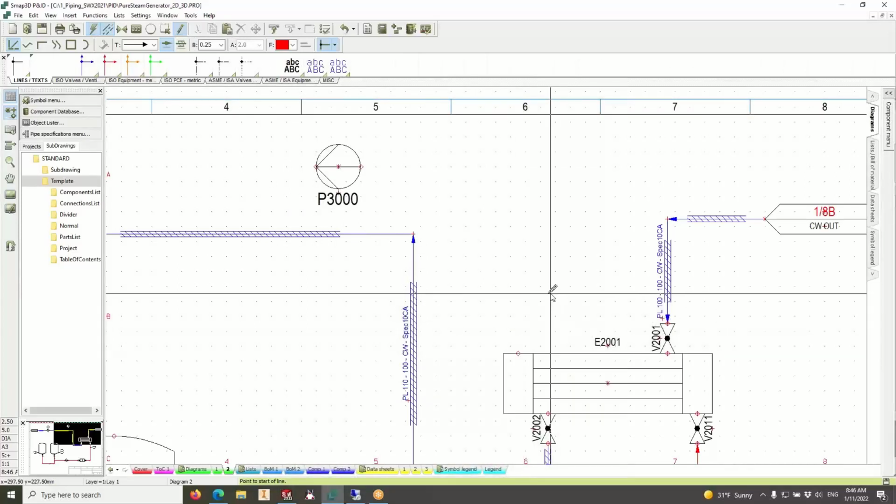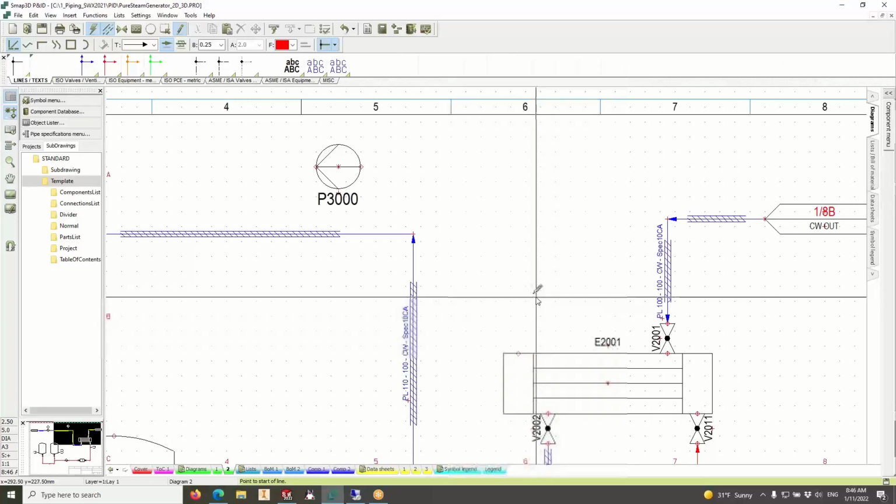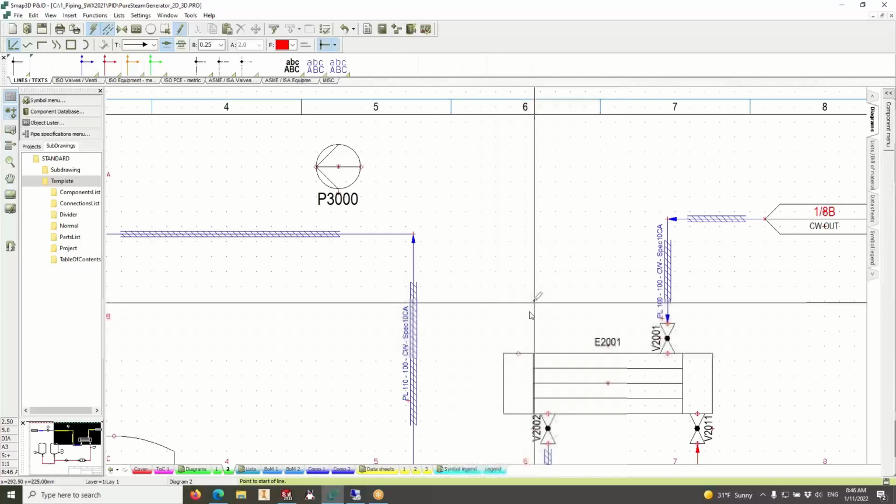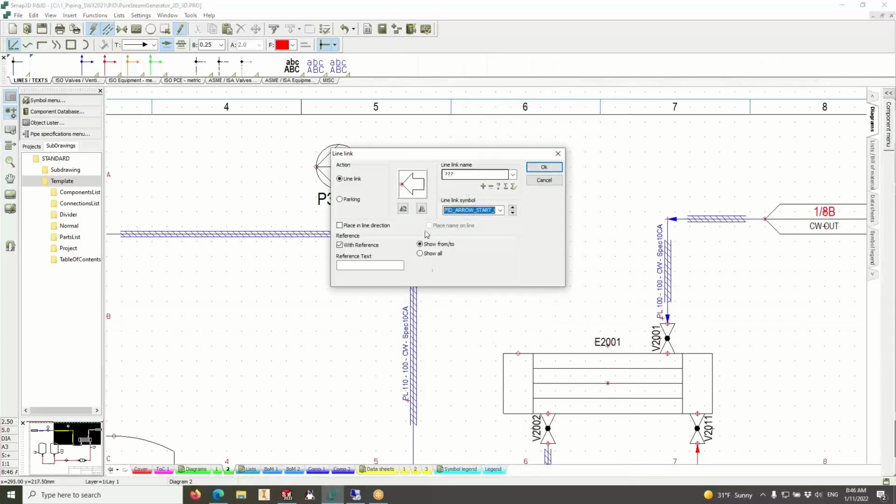Okay. Now, we are a schematic capture tool from the ground up. So we're not an architectural CAD tool that then we've added a library of symbols or a library of blocks and call it a P&ID. We are P&ID from the ground up. So if I try to draw a pipeline that doesn't connect to something, the system's going to warn me and say, well, that's not normal.